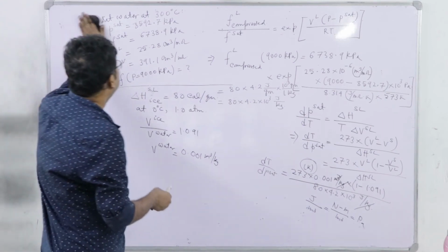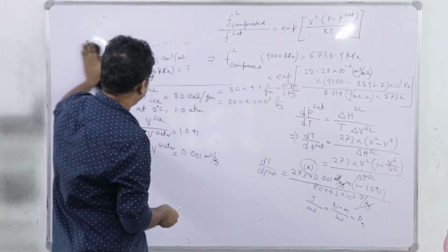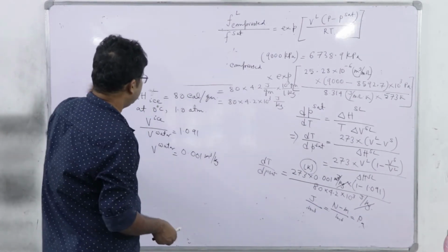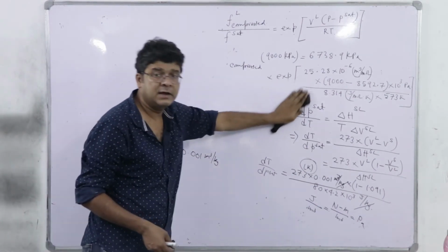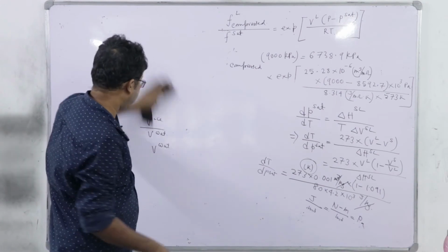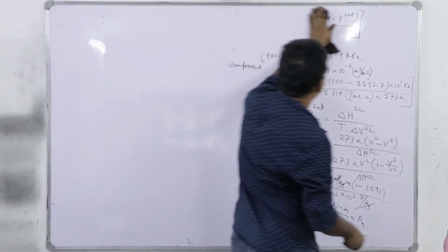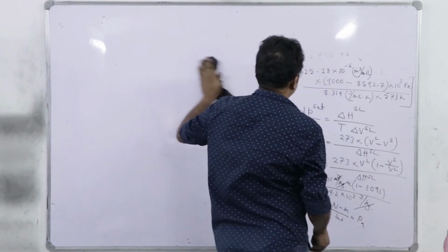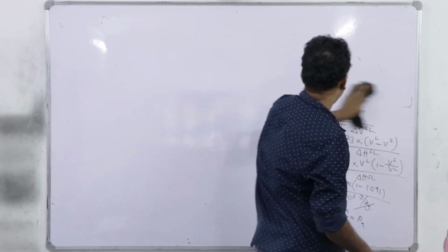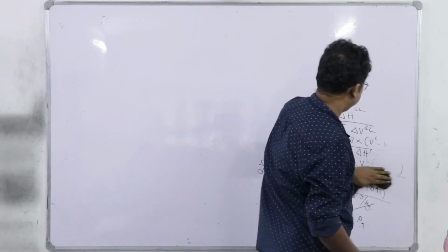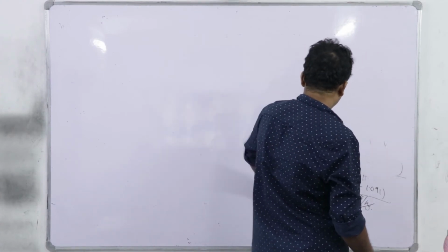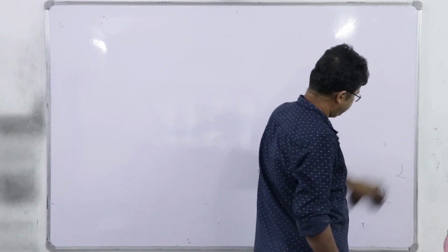So, the answer will be in Kelvin per Pascal. Here we have to use Clapeyron equation and not the Clausius-Clapeyron. Clausius-Clapeyron is only valid for liquid to vapor or the vaporization curve. It gives the saturation pressure temperature relation for vaporization, or rather this liquid vapor equilibrium or boiling.